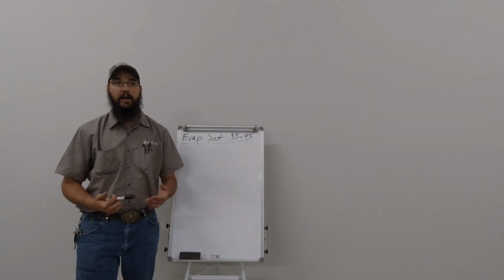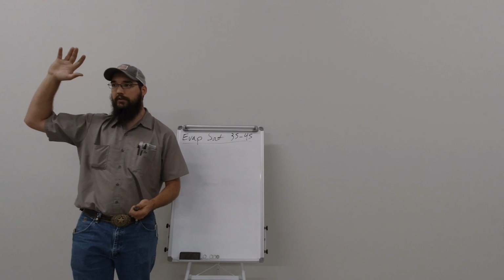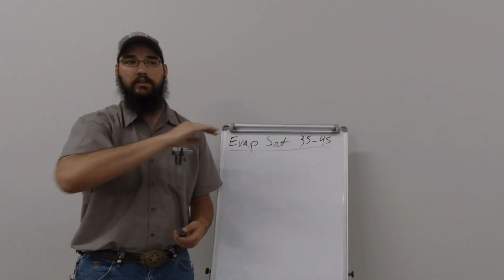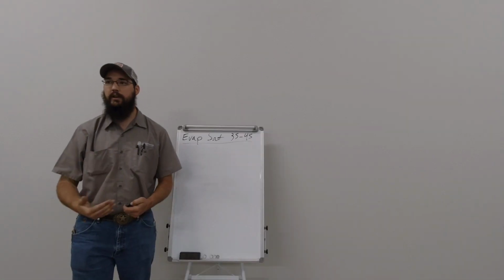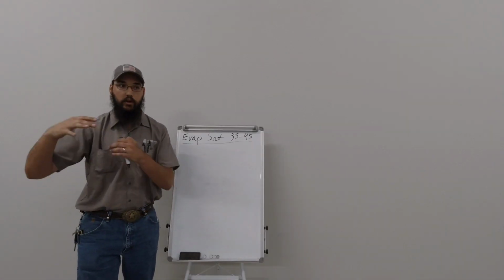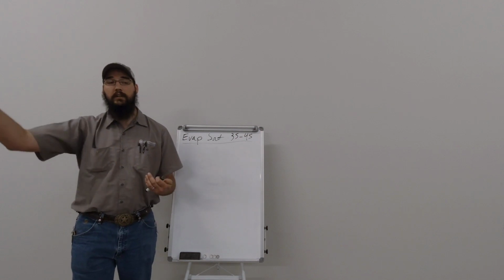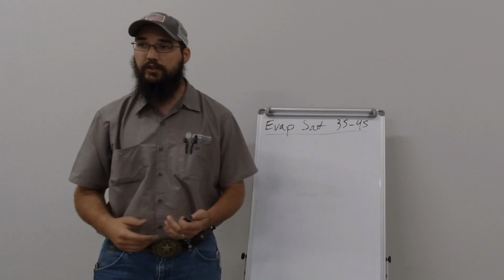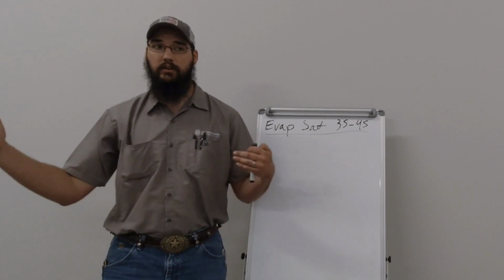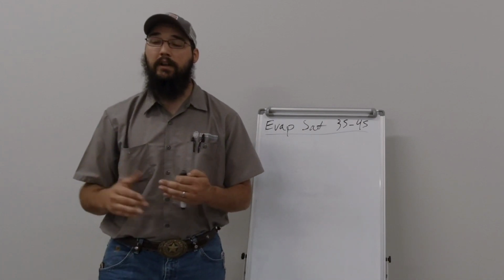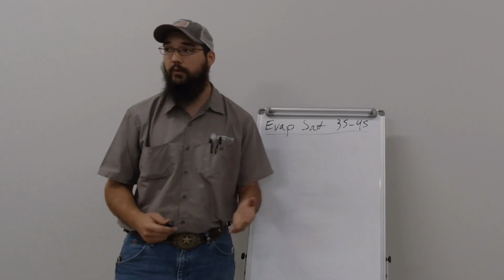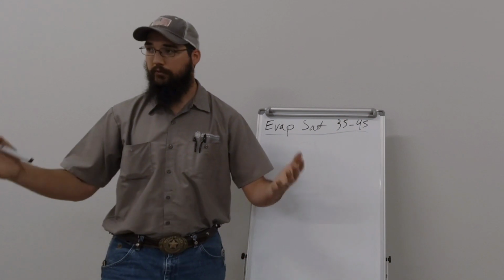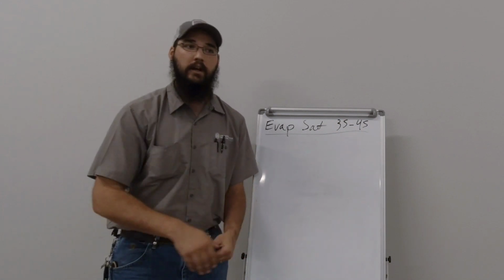Because that ratio is factored, anybody know the formula? How is compression ratio factored? It is discharge pressure divided by suction pressure. That gives you your compression ratio. We want that ratio lower. To do that, we have to get the head pressure lower and also increase the suction pressure to decrease the gap between them, right? So that's what high efficiency systems do. They've got huge, massive, efficient outdoor coils. Their sole purpose is to run a lower head pressure.